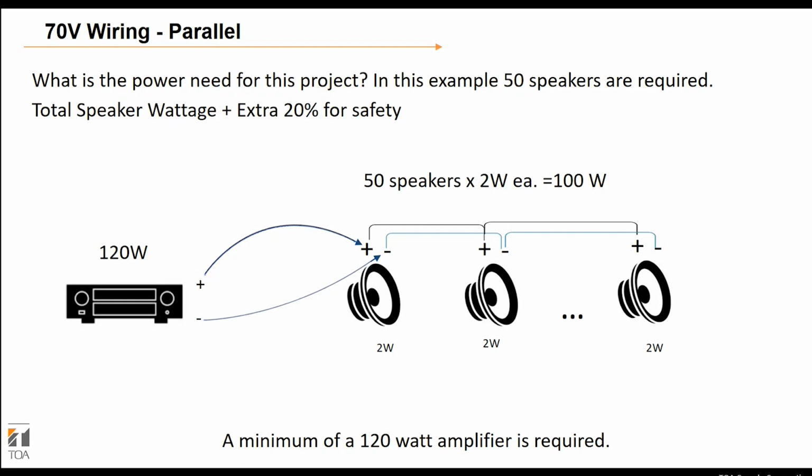So in this example, what is the power draw needed for this product? What kind of amplifier am I actually going to need? So we have 50 speakers in this system, and they're all set to 2 watts each on the wattage tap, so that equals 100 watts. If we want that extra 20 watts headroom for safety, then we need a 120 watt amplifier.